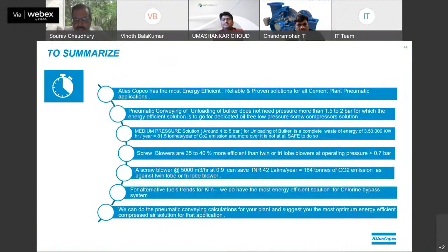Now, just to sum up, we just talked about a few things. I'm concluding my presentation: at Atlas Copco we have all the necessary technologies and products for each and every application of cement. Pneumatic conveying, specifically conveying from point A to point B or unloading applications, normally does not take pressure more than 1.5 bar. Considering the line losses and the bends, maximum 1.7, 1.8 bar.